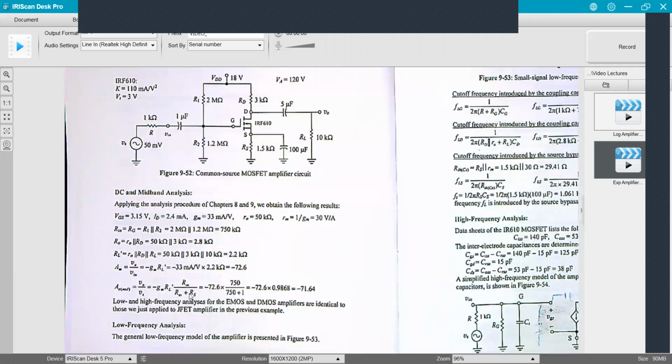It's like, well, why not? Well, our voltage divider here, RN over RN plus RS, these guys right here are huge compared to this. That's the other reason you want to use large resistors here, is that you have a large input resistance, okay, 750K compared to 1K. So then our gain from here to the output is pretty close to the same.